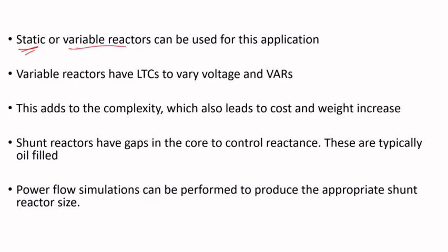You want just some of it, because it depends on the voltage rise. But you can have a variable reactor for this application. Variable reactors basically have load tap changers, LTC, which vary the voltage and VARs. Basically you only include so many turns in the circuit, it depends on voltage, so it will be programmed, and if you have 10% up and 10% below nominal voltage,